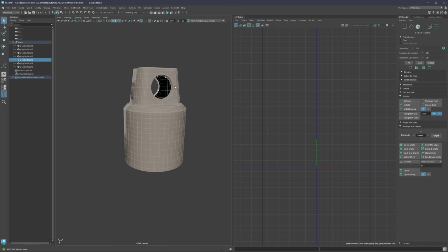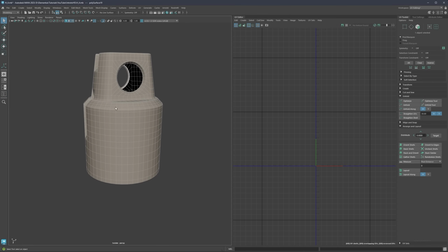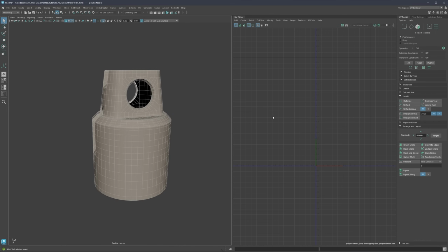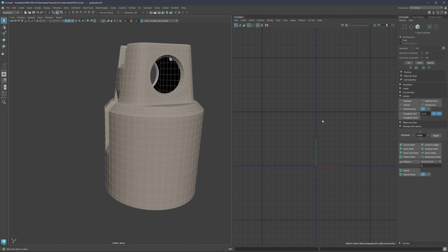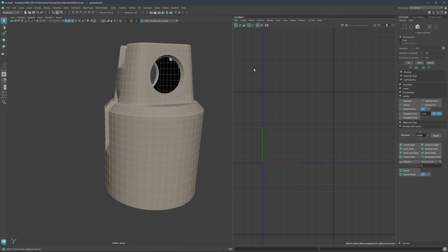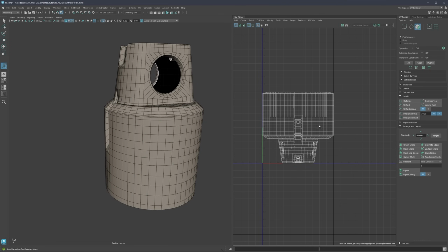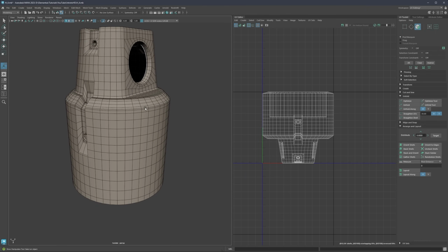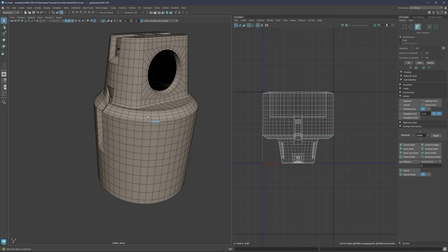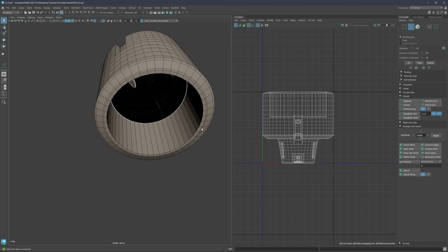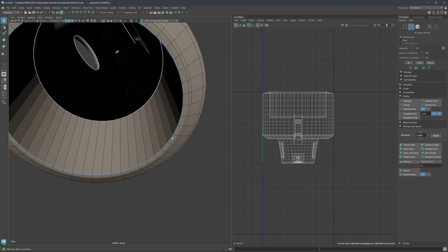And let's now go again into the object mode and slowly start cutting this out. And let's go now into the edge mode, but first just make sure that we have any kind of UVs, because if you start cutting now, there's actually not going to happen anything really major. So you need to have any kind of UVs, and let's just simply hit planar. It really doesn't matter which kind of UVs come here. So let's now continue, and let's start from the easiest part, which is going to be here at the bottom. Again, the depth value is going to be here.